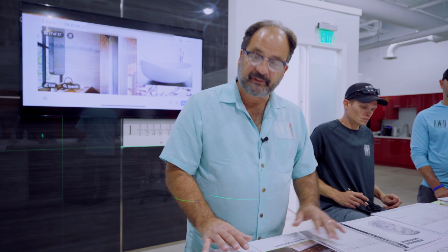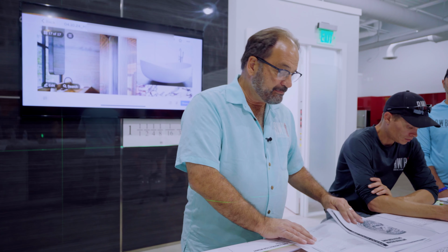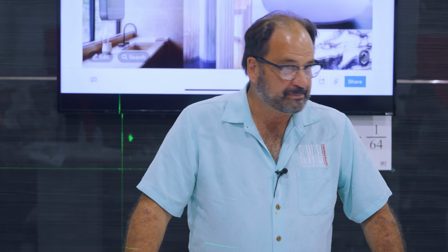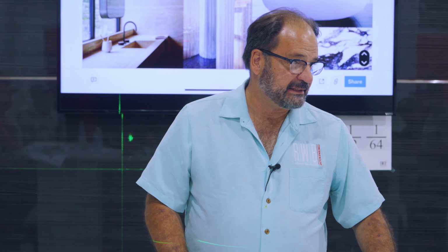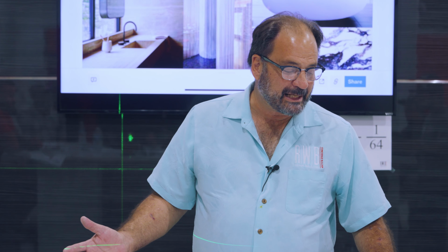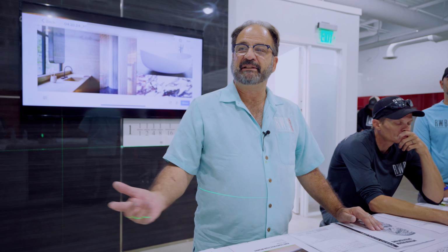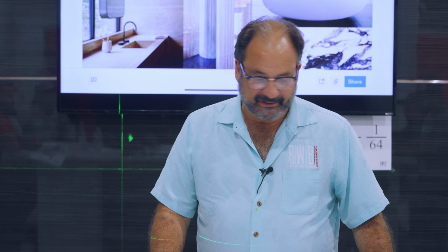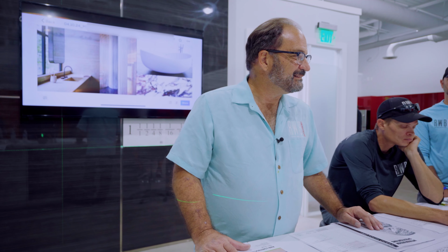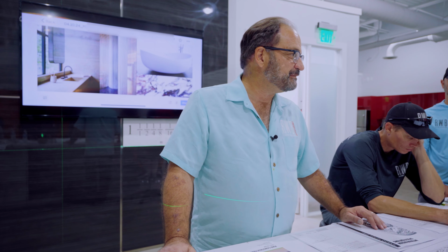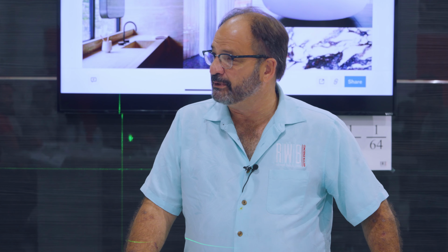So, key points for this week are this. Make sure you have all the information you need. Make sure you have a spec book. Make sure you have selections on appliances, plumbing, electrical, lighting. One of the common things we have going on now is some fixtures are 0 to 10 volt, which means when you're running wiring, you need to add another line or it won't dim properly. One of the common things is that the designers don't know that. So you tell them while you're wiring, I need to know what fixtures are 0 to 10 volts. And then you wind up getting on the phone with the supplier because the designer has no clue what you're talking about.